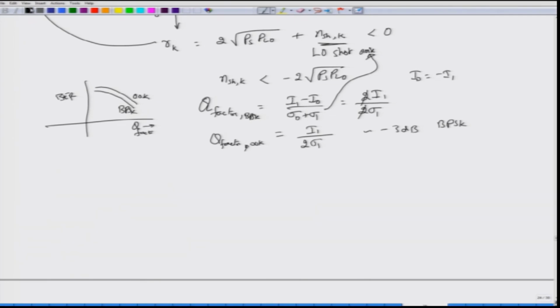Now, from BPSK you go to this 4 PSK, here the constellation points are located here, and then the decision regions will now be located at these points. So, if my received signal happens to lie within this particular region, then anywhere if it lies in this region, then I will declare that one as this bit sequence. On the other hand, if my received sequence lies anywhere over here, then I will declare this one as corresponding to this particular bit sequence. Similarly, you have additional 2 regions as well.